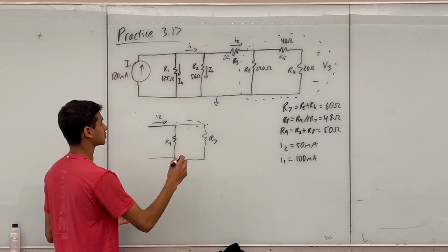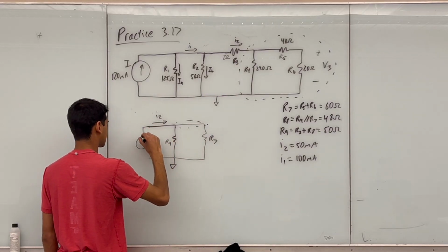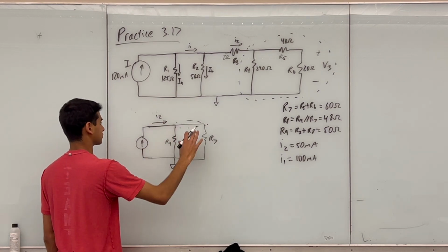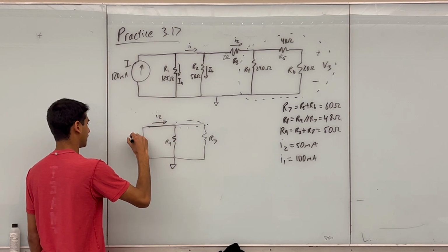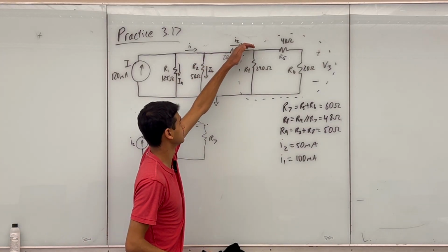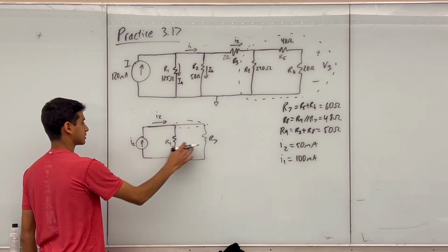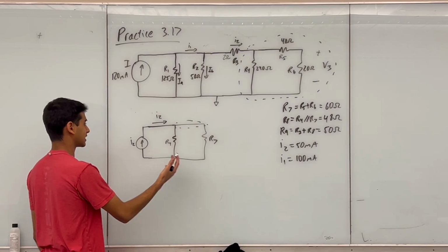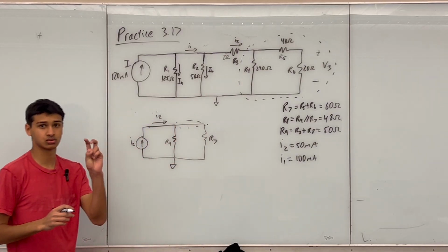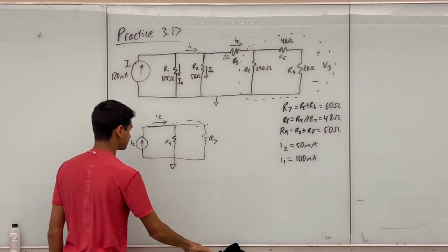And that'll make a lot more sense if I redraw this part of the circuit like this. So I have a current supply, kind of. Now this is not the actual circuit obviously, but this is just another representation with a value I2. So this value I2 is entering this node here, and it's splitting between these two groups of resistors. And since I have that, I can actually use current division with I2 as my source, even though it's not this initial source.